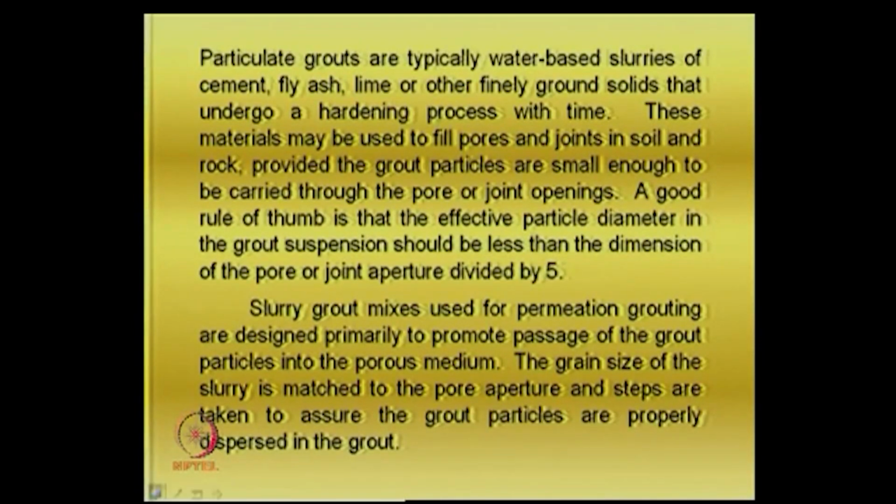Steps are taken to assure that the grout particles are properly dispersed in the grout. Sometimes you may have to have dispersing agents to see that it is stable.